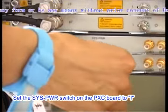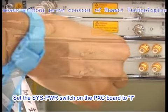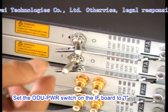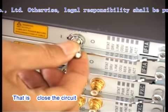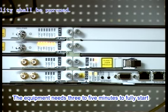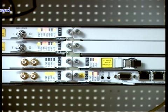Set the system power switch on the PXC board to I. Set the ODU power switch on the IF board to I, that is, close the circuit. The equipment needs 3 to 5 minutes to fully start.